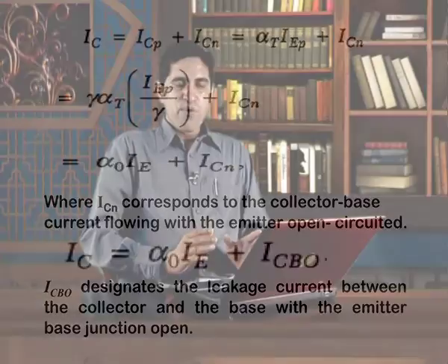If you see our common base current gain factor alpha 0, it is always less than 1. So, in this configuration we will not get amplification, because ICBO is the leakage current, very small, generally in microamperes, and alpha 0 IE is in milliamperes. So, because the alpha 0 factor is less than 1, close to 1 but always less than 1, in this configuration we will not get amplification, we can only use it for switching applications.